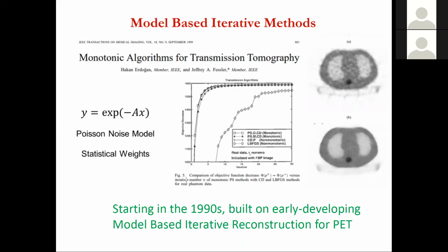The better the model, you can also help with things like in-painting, which means you introduce what you would have seen in these elements where it's been corrupted by things like metal artifact and whatnot. Now, you need to be careful when you start using some of that on motion correction, because you make something that's inconsistent. But if it's just lost data, where you're filling out the rest of the sinogram with what it would have been from ideal data,